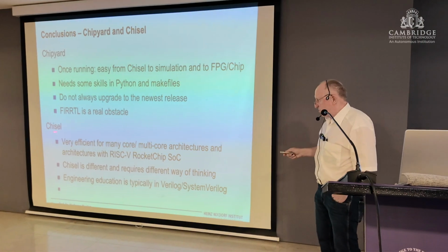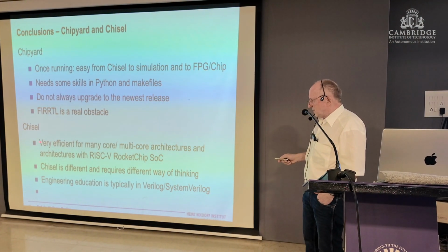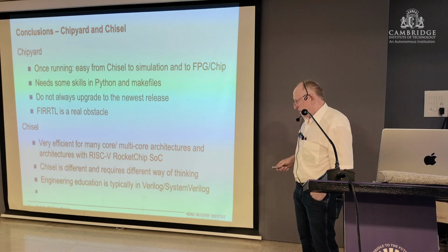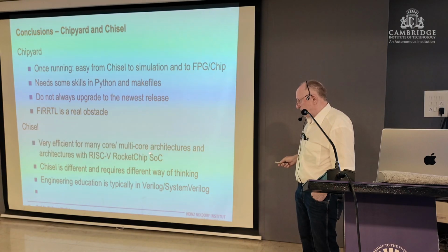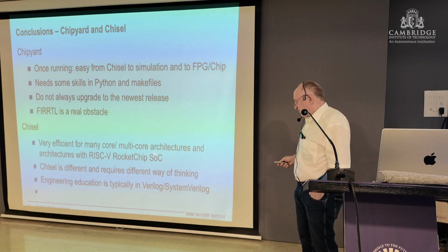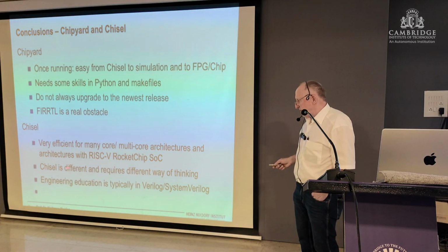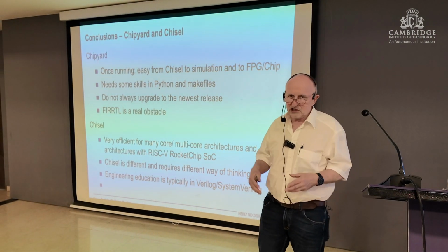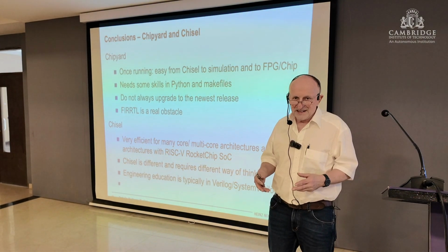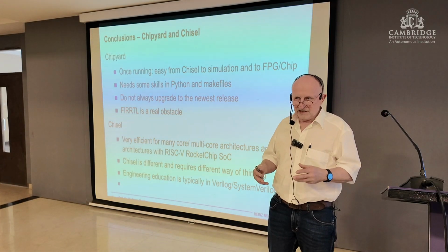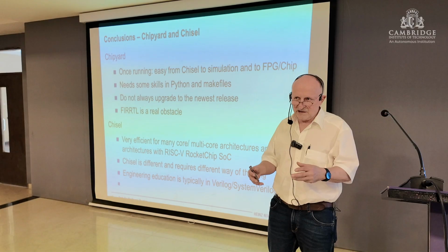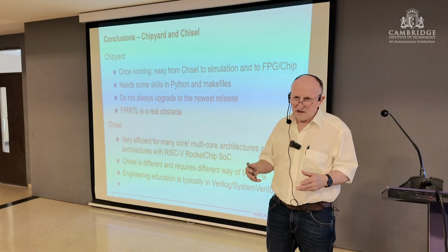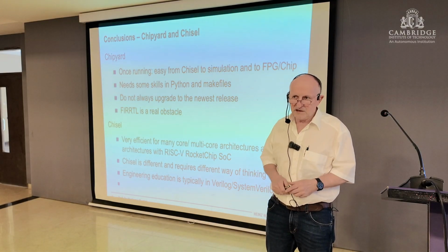With respect to Chisel, it turned out to be very efficient for multi-core or many-core RISC-V architectures. So we have very good experience. It's very fast. However, we see the engineering problem. Chisel, the perspective and working with Chisel is not engineering oriented. So there you basically have to think like a software engineer and not like a Verilog engineer. This is a real problem, but we are getting closer for it for the education.